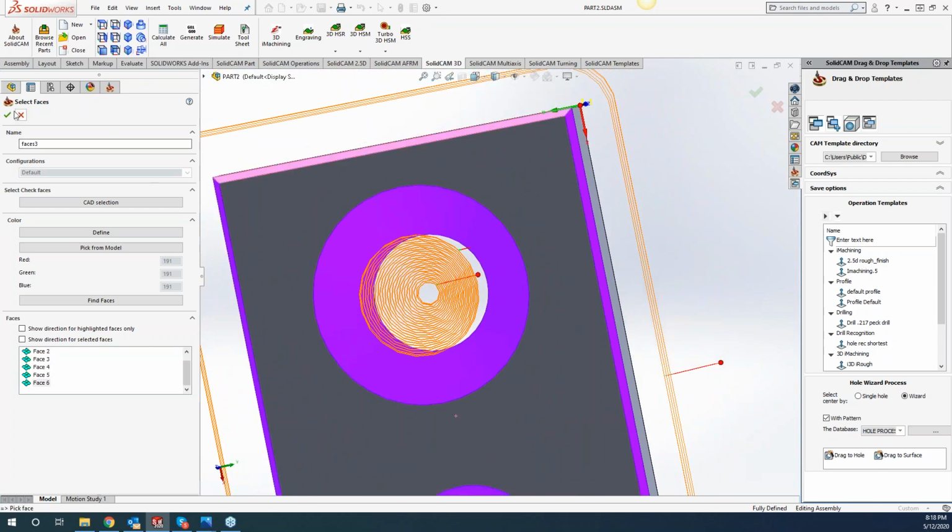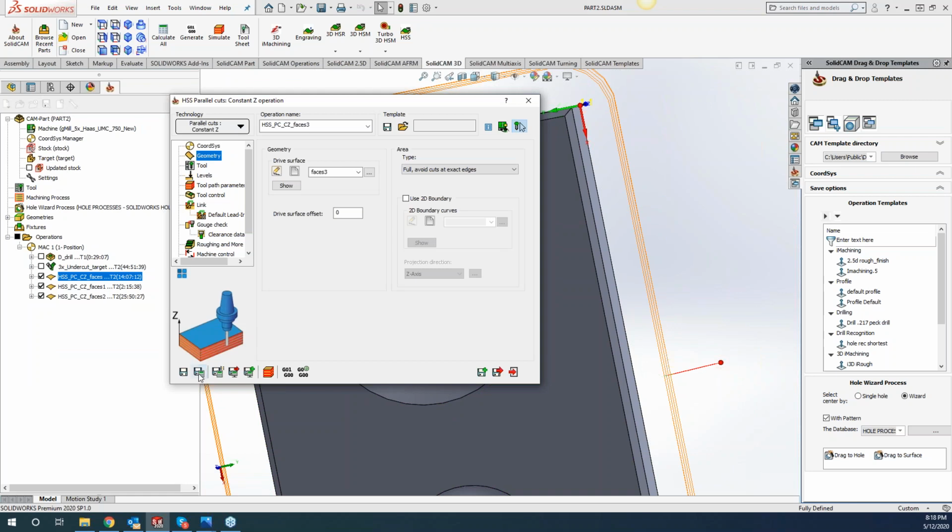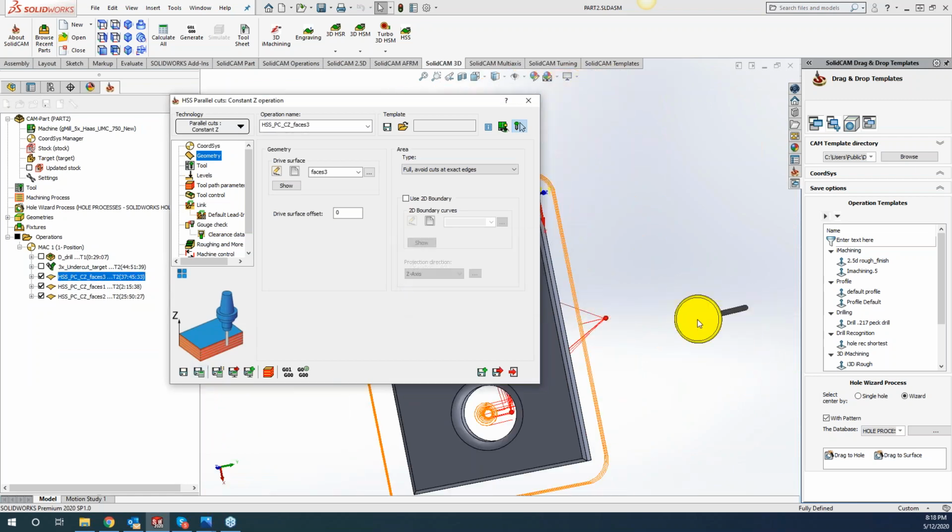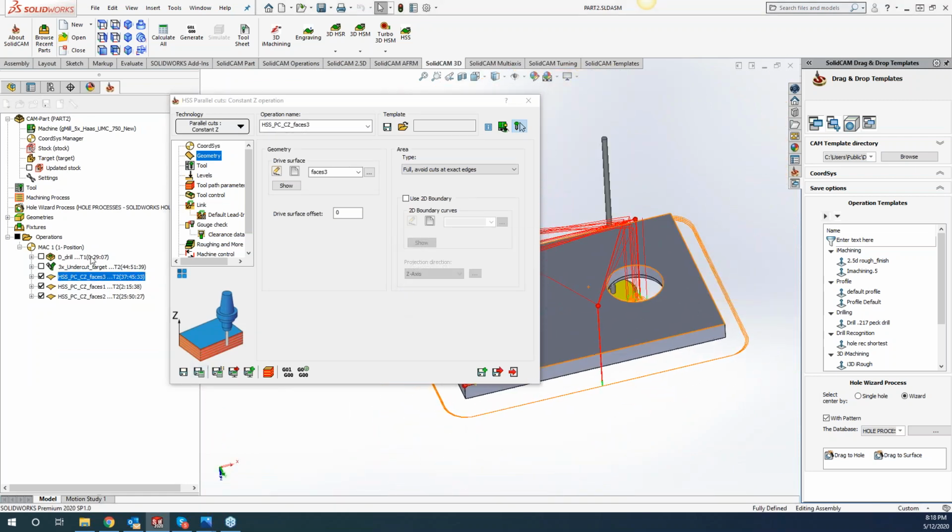But to your point, Kevin, with the undercut milling, it really shines if you have surfaces that are running into other surfaces. Maybe you have some features or bosses that go into that undercut or extrude out from that undercut. Yeah. And you want the tool to follow that constant Z profile around all the surfaces instead of this basic surface geometry. Yep. Then by being able to select the target model and have it analyze every feature of it.